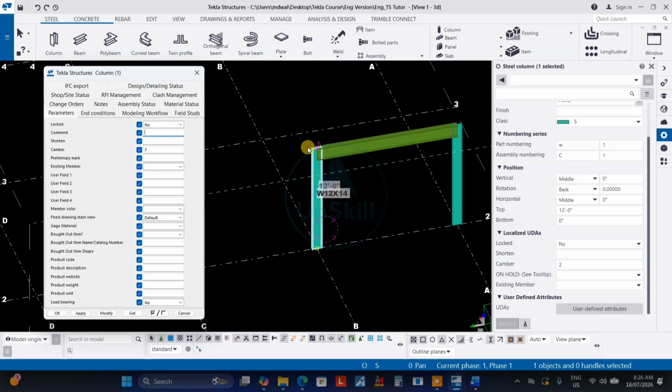Earlier I gave one example for the connection of that beam and the placement of the shear plate. I moved it by 15 mm or 15 inch or 10 inch like that. How would he know about that? Only if you keep it here, he will know that this is on hold and why. Or sometimes the checker also keeps a note here, like checked. So whatever the situation, you can use this comment option.